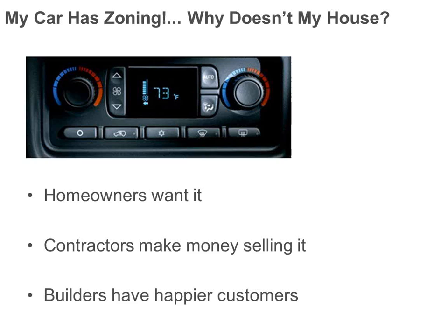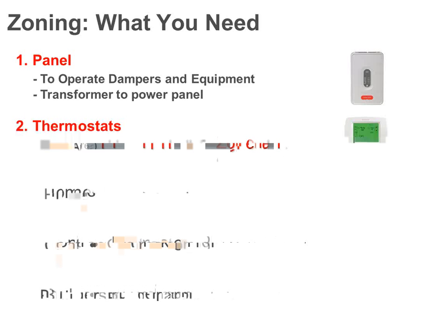So a normal zoning system, here's what we would do. And this example here is with a Honeywell zoning panel, right? So we'd pick our zoning panel depending on how many zones we needed and how many stages of heating and cooling and all that good stuff. We'd pick our thermostats, right? And you could pretty much choose any thermostat you want on a Honeywell zoning panel. Although I will remind you that Energy Code in Illinois, residentially speaking, since 2009 has required programmable stats.